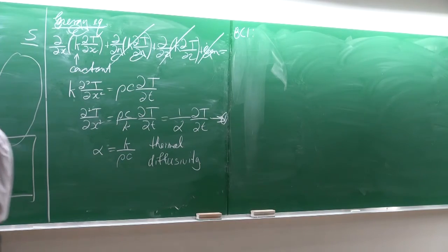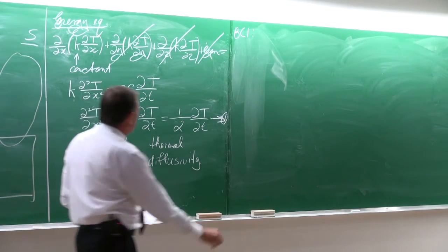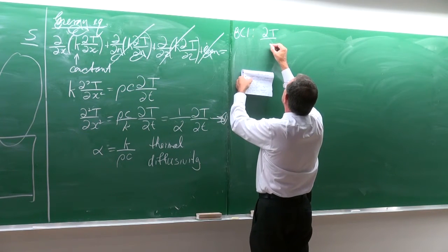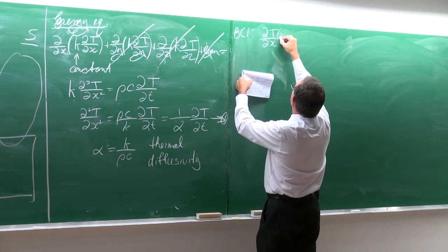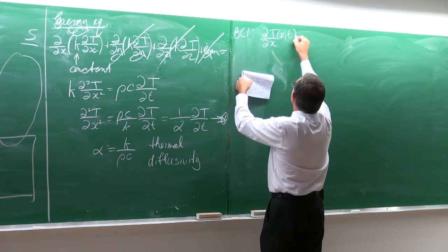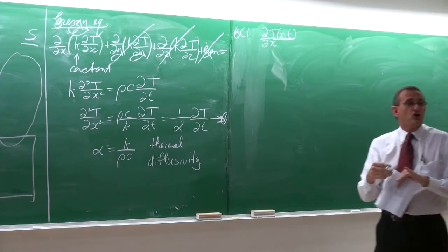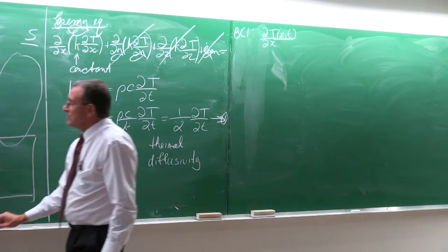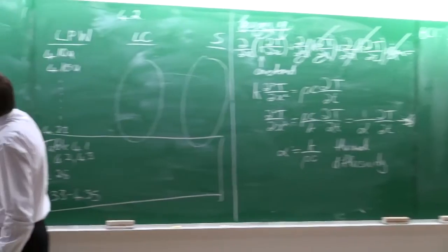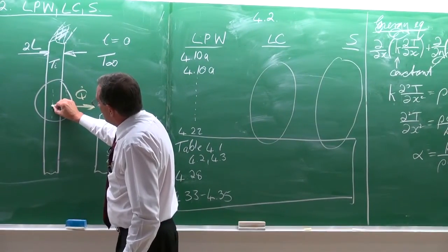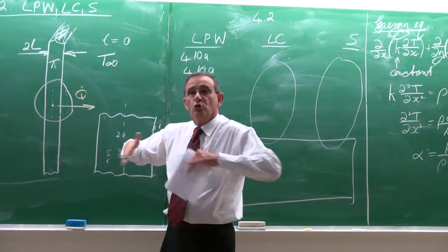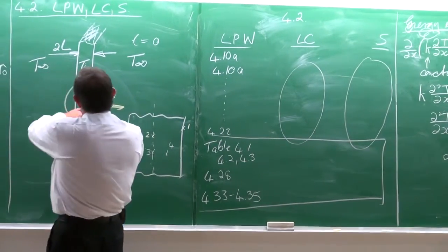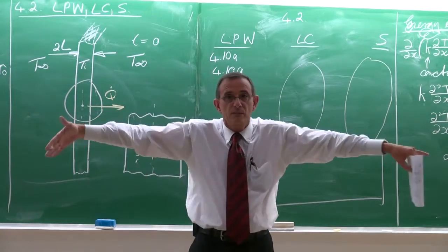So, the first boundary condition that we know would be to look at partial dT/dx, for the temperature at point x as a function of time. Okay, now the first thing that we know is that if we look at this body and it cools, remember, T environment on this side and T environment on this side. So the heat transfer rate would be the same in both directions.